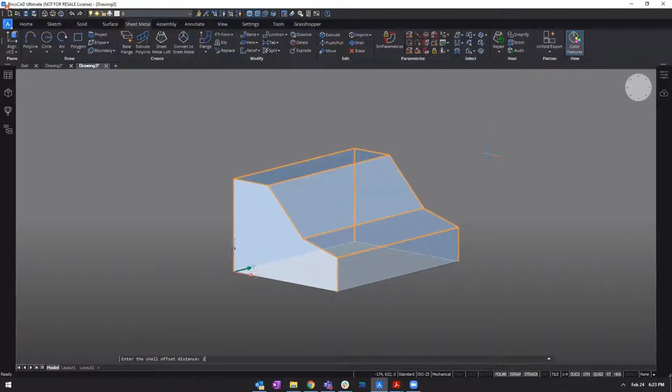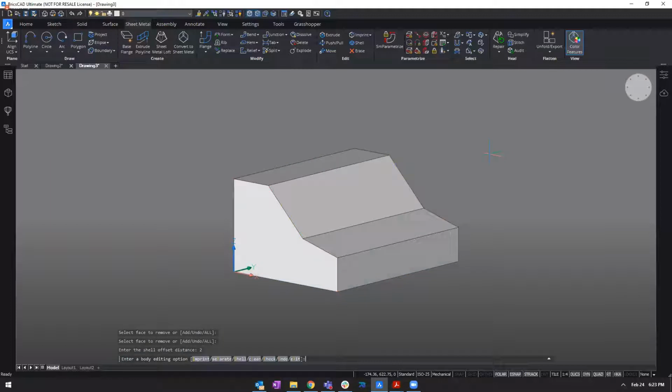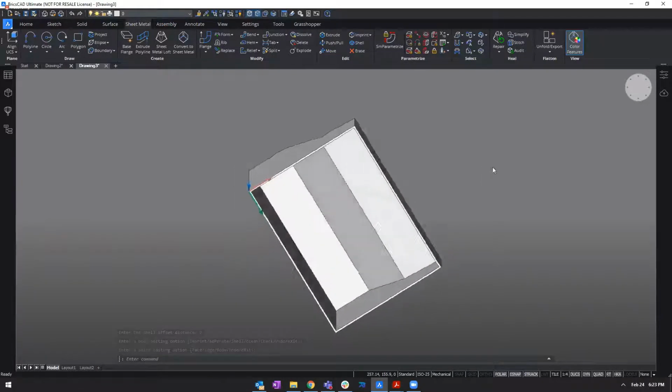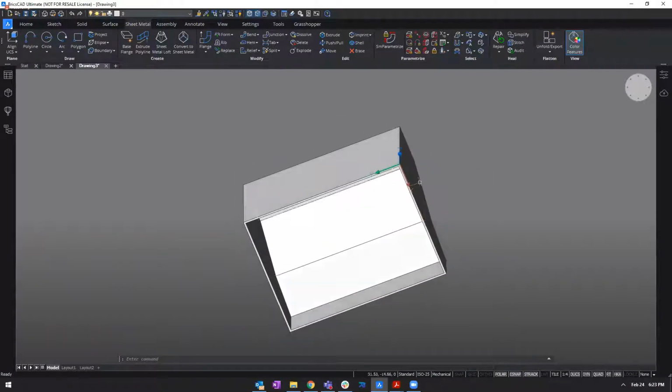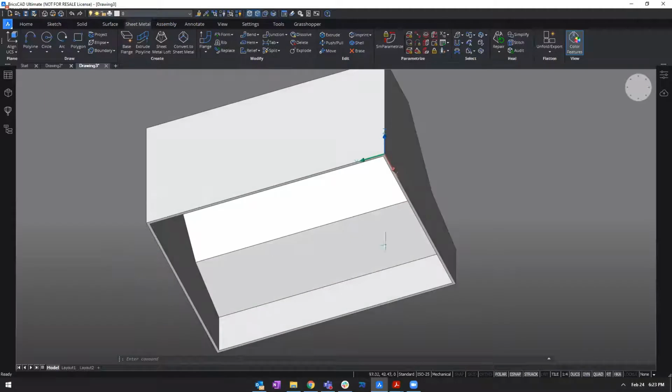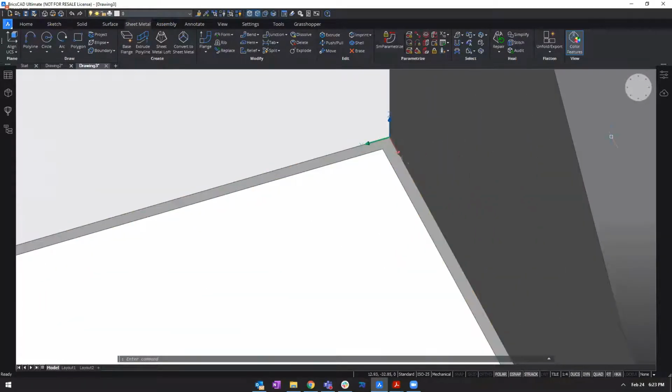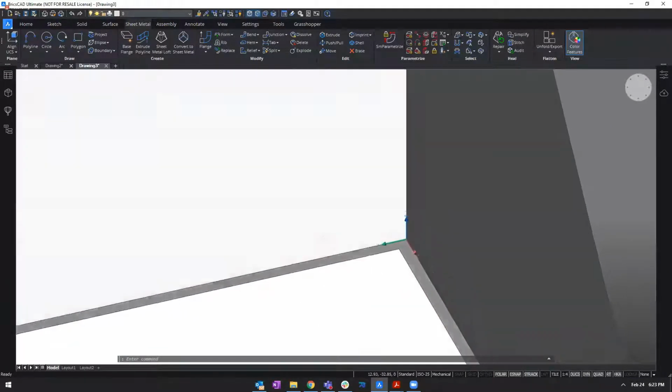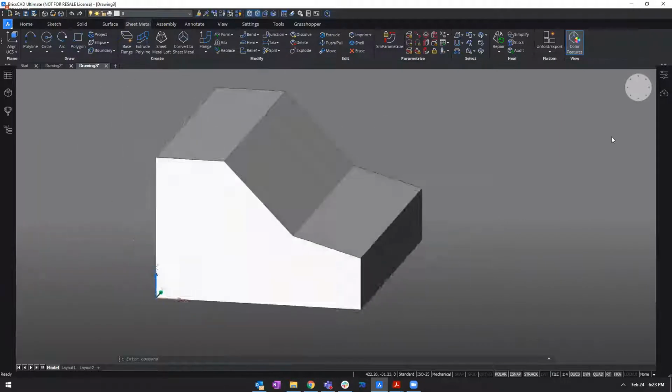it's a bit hard to see. I will choose an offset of 10 millimeters. Now I will select this polyline that was created. And using the solid extrude command, I will extrude a hole into my solid.